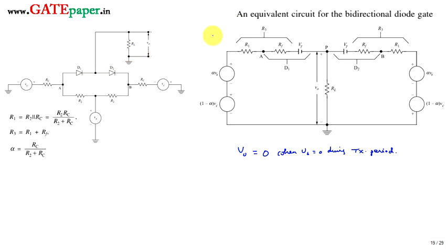Remember that one. But you may think, what about this V gamma? V gamma also, if you check, is plus minus. Now node P, that is the output node, is connected with the negative polarity of V gamma with respect to D1 and the positive polarity of the diode with respect to D2. That is, again the cut-in voltages are applied in equal amount but in opposite direction. So they also don't affect the output. So no need to consider this V gamma during the transmission period.